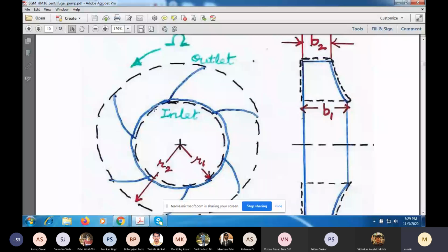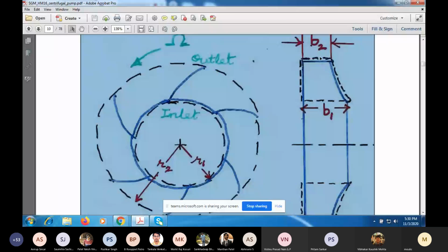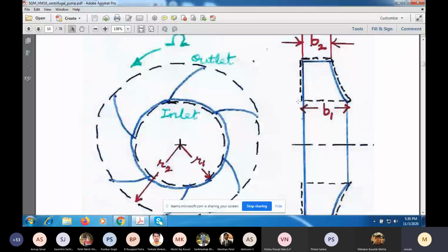So at this location r equal to r1, in most cases, if you say the model is an inviscid model, the v theta 1 will be 0. But at the outlet, there will be a non-zero v theta. So v theta is not generated by the no slip condition, it is by the no penetration boundary condition.